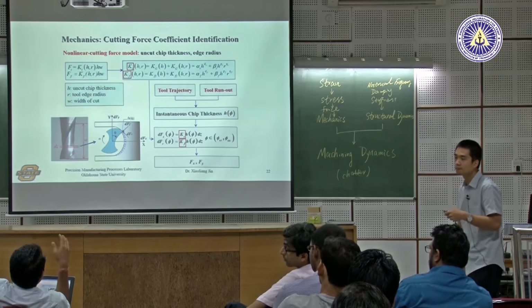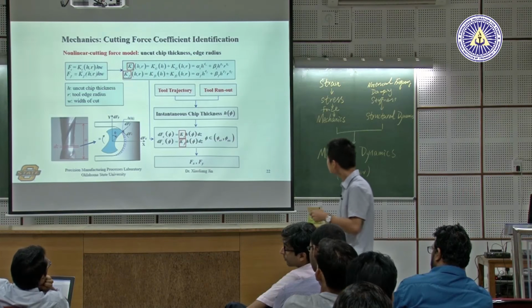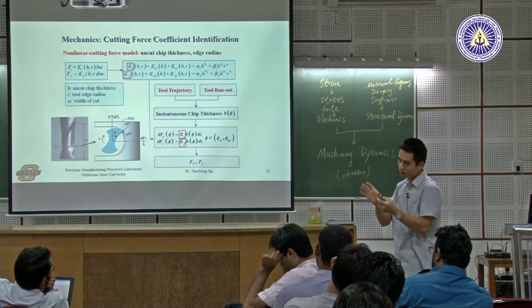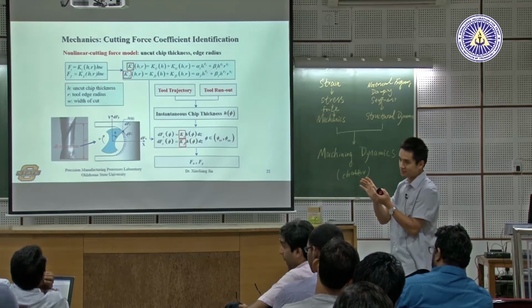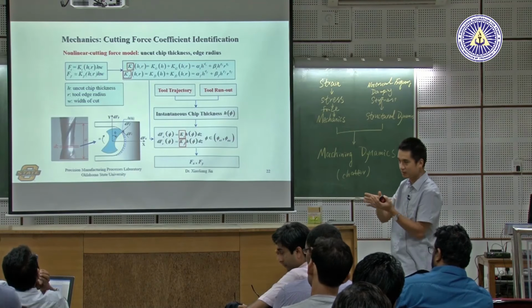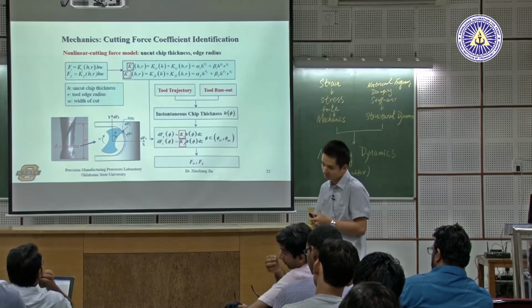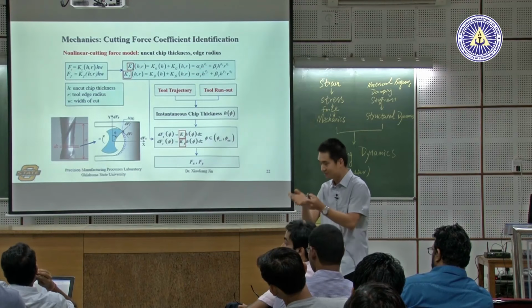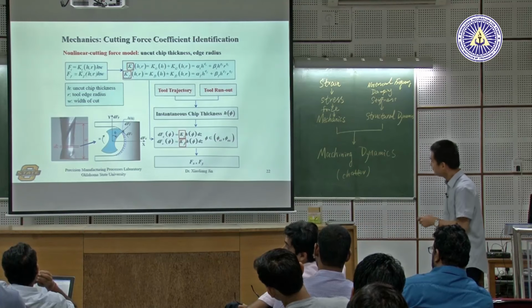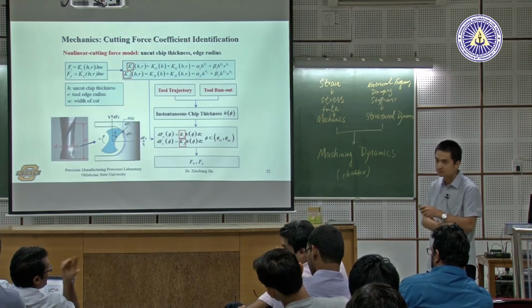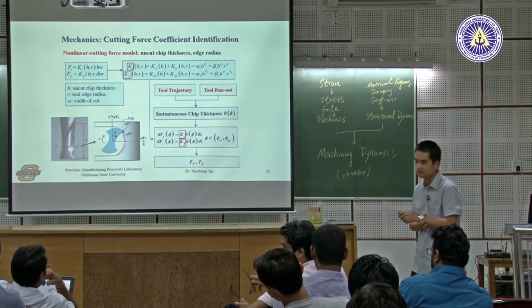Any particular advantage? I can do experiments and fit the same data. You're right, but from experiment, we can only fit data for that specific cutting condition, right? But on the simulation side, we're able to do any range, for different materials, with different ideal material properties also. Yeah, that's right. You need Johnson-Cook parameters anyway. Yeah. You can do experiments either on Hopkinson bar or something. Yes.